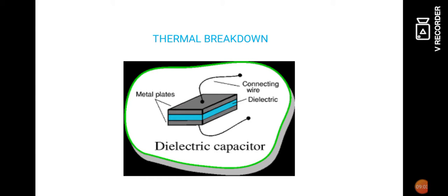Now let us see the figure of thermal breakdown. Here we have to consider the dielectric material, a dielectric capacitor. When a huge quantity of current is flowing through this dielectric material, it starts melting. As a result, it will start conducting.